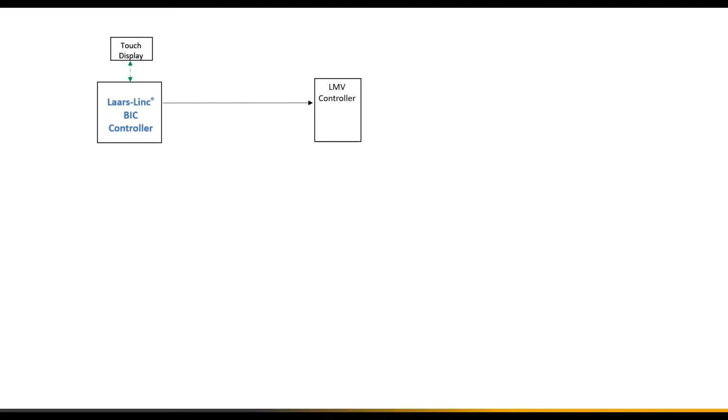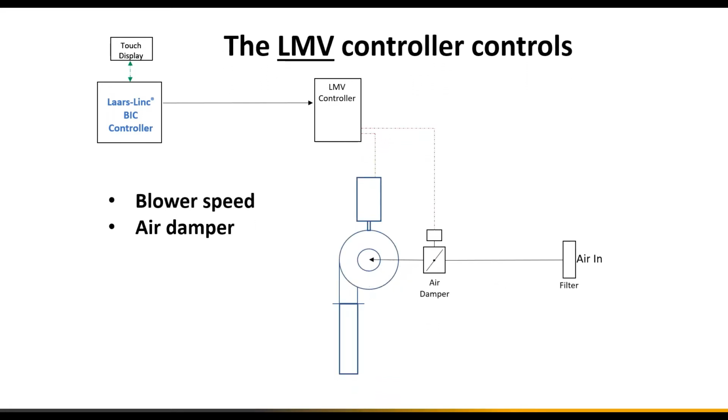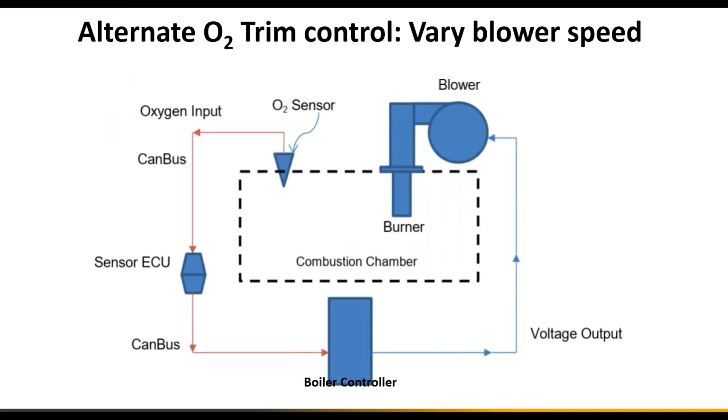Yeah, you can click through these fairly quick here. So we have an overall control system, looking at the gas, looking at the air, setting those positions based on firing rate, and then the O2 sensor in the control system making a fine-tuned speed adjustment. Moving on to the next one. Another manufacturer, very similar setup.